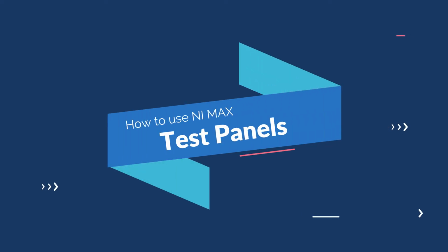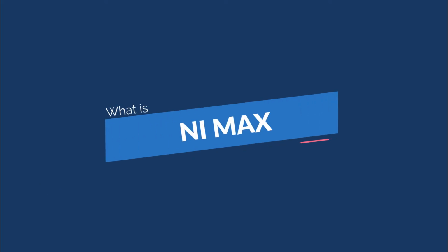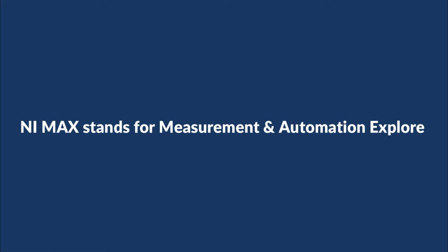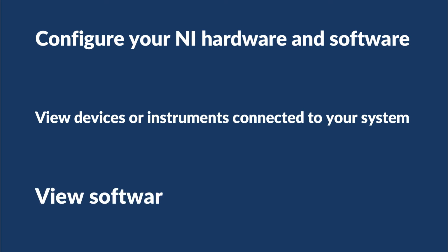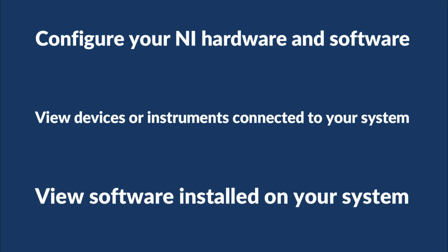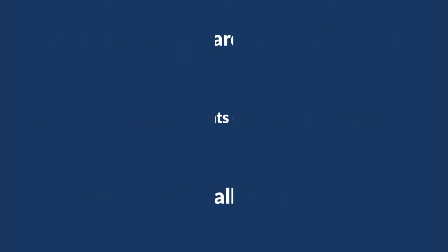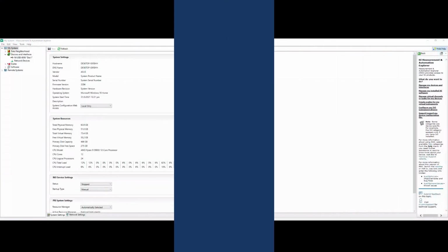In this video, I'll be showing you how to use the test panels in NIMax. NIMax stands for NI Measurement and Automation Explorer. With NIMax, you can configure your NI hardware and software, view devices or instruments connected to your system and software installed on your system, and many more.